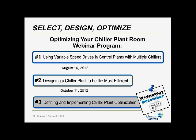Whatever condensers you got, maintain the delta T. As long as they're balanced to start with, then they ought to ramp down at the same basic proportion. So maintain delta T is a good way to do it too. That's the same thing as saying I want to reduce with load. So in our case, we would be reducing to our 80%, utilizing the maintain delta T.